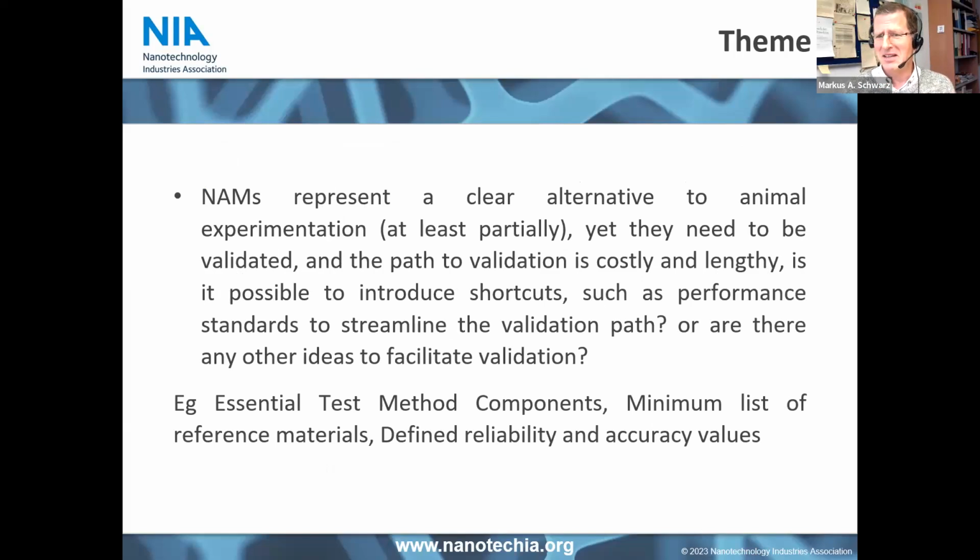The kind of tubes I'm busy with are very long and entangled, and right away they are not dispersible. You cannot disperse them without destroying them, because if you apply too much ultrasonication, they will break, and then you are testing another thing.